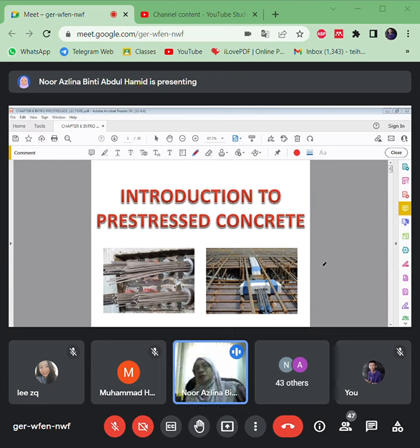After this, if you work at precast concrete, you will see all the production process for the pre-stress, how they pull all the reinforcements, all the tendons, to certain loads, and then after that there will be a process for cutting all the tendons. Lastly, they put in sockets and everything, grouting and everything. Okay, that is the basic thing about the pre-stress here.